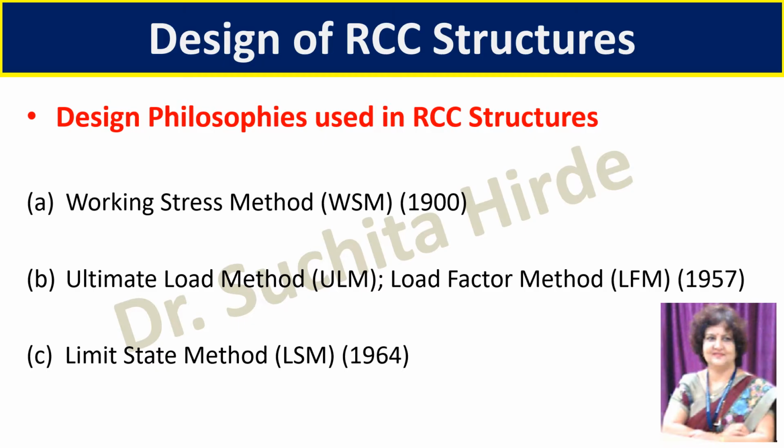Since there were some drawbacks of the first two methods, that is, working stress method was giving uneconomical design and the design made by the second method, that is ultimate load method, was not serviceable. That means there were large deflections and vibrations in the structures, and therefore the third method was developed, which is limit state method. This method avoids the drawbacks of working stress method and ultimate load method.